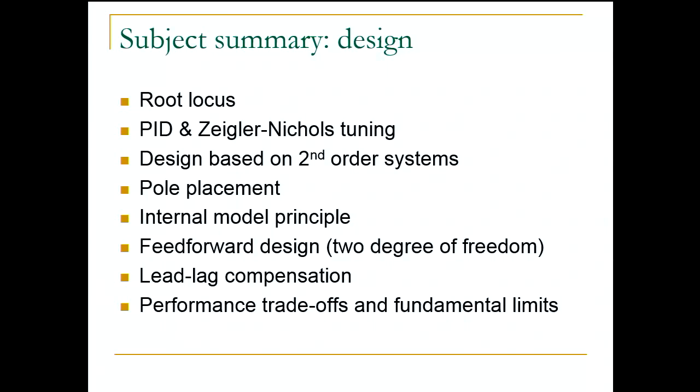So also this morning we were looking at performance and robustness, right? We learned about the small gain theorem, which gives you ensured robustness, and we also saw how any perturbations in the plant affect your sensitivity transfer functions, and typically different performance characteristics of the system can be captured by the properties of the sensitivity functions, right?